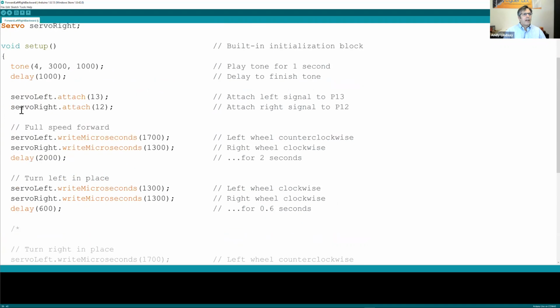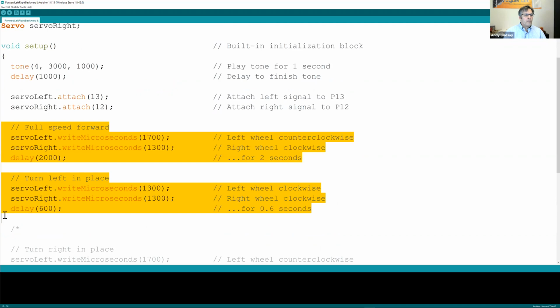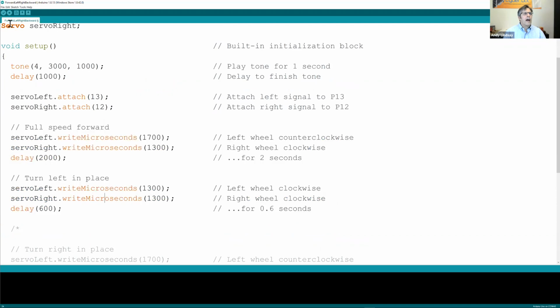When we do that, all we want to see is our robot moving forward and then turning to the left. And if you want to save desktop space, you can reduce the forward to whatever you want. Like I'll make mine 1500. But the 600 we're going to tune to try to get it to do a 90-degree turn.